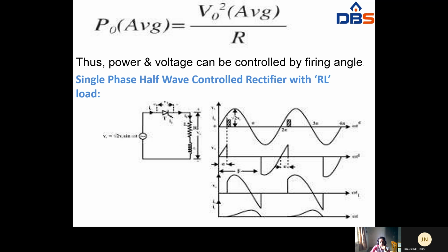And this is a thyristor voltage. Okay, so the thyristor voltage VT, that means the output voltage, at triggering of the thyristor, the load voltage will increase, and it will come to 0 at pi, and in reverse bias it will commutate for some time because of the inductor, and it will come to 0.